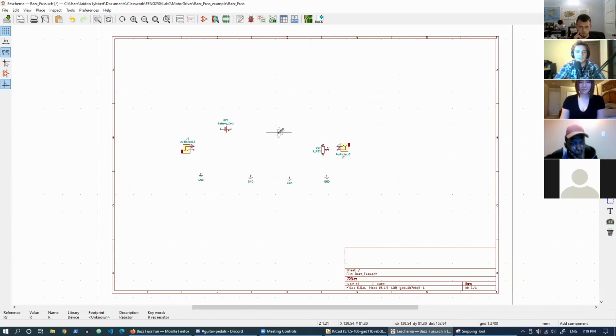So it doesn't matter as much what components you're choosing here in this schematic, like this layout editor. What's going to matter more is the footprints that you assign to these things, because the footprints define the physical size of the component on the PCB. These are just a logical arrangement of components. So I'm going to place this here.